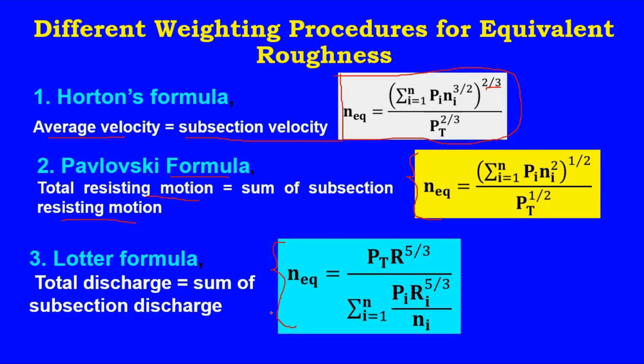Either you select the whole section method or the partition method in the above equations, finally you will adopt the best or the maximum discharge conveyed through the compound channel. Once you compute the equivalent roughness, which is especially used in the whole section method, we will consider the equivalent roughness rather than N1, N2, etc.